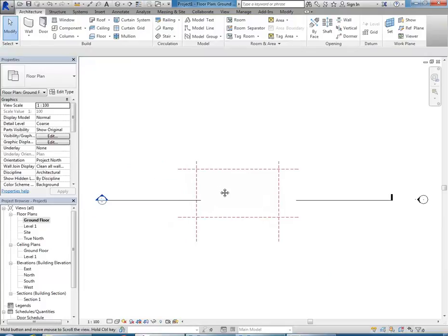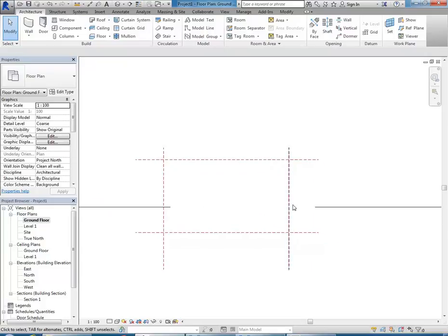And so it's good to think about this process whenever you start something in Revit, setting out your main measurements, and in this case it's the measurements for the interior space. And then your wall thicknesses, I think maybe aren't dimensioned on here, and it's absolutely fine if they're not because of the way I'm going to draw it.